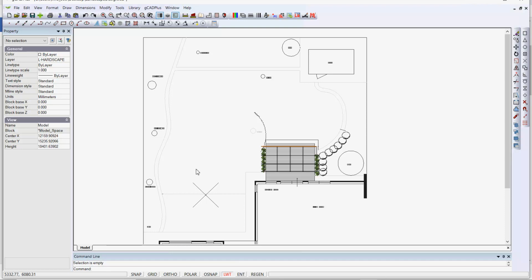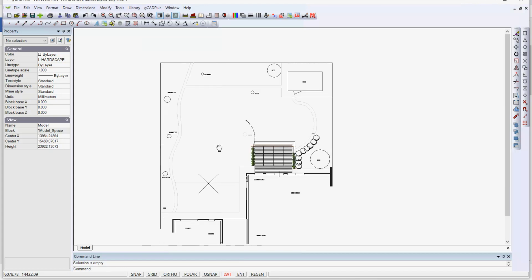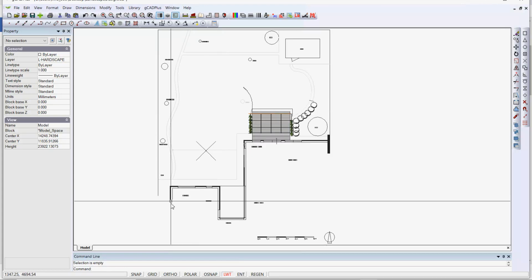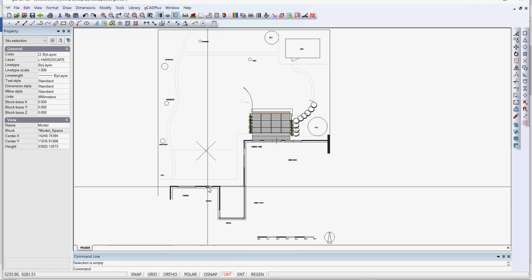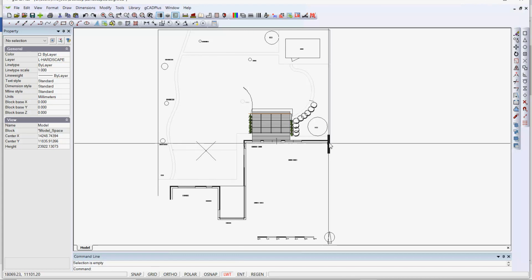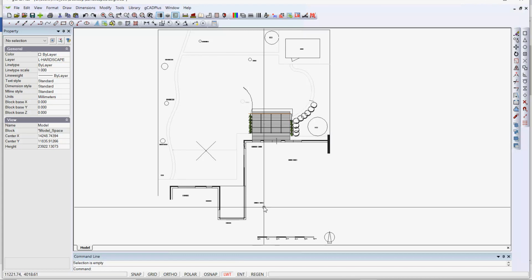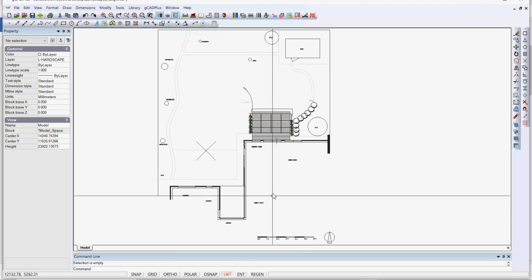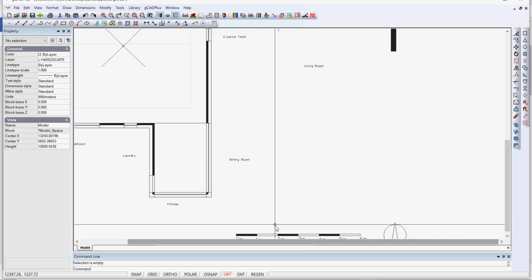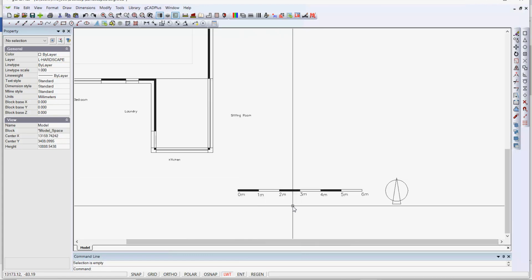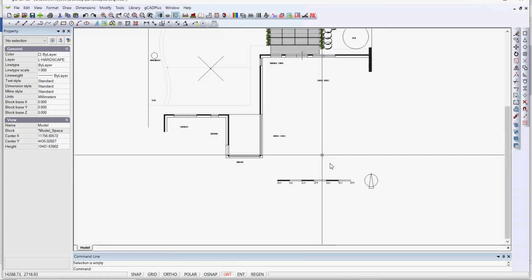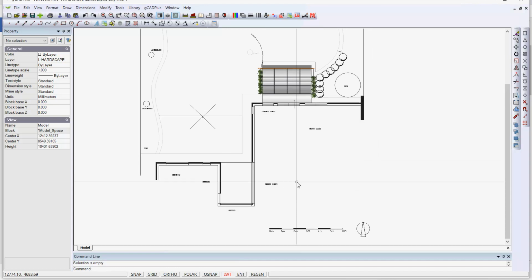Well, here's some landscape design work, some preliminary work, some ideas for a rear garden. Let me just click in here and zoom out a little. So we have measured the footprint of the house, denoting that rear area. There's a scale in here. If we zoom in there, that's a 0.1 metre, 6 metre scale. So we have a fairly good idea that this has been drawn full size.